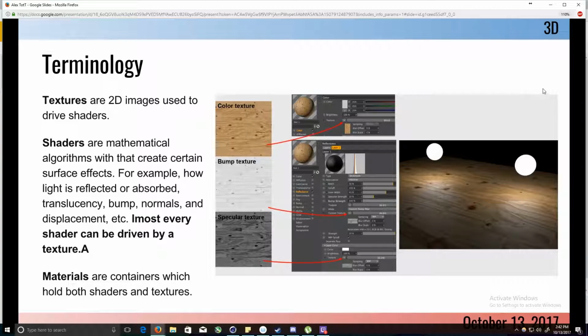So if you look at this little image, I have these 3 textures. One is a color, one is a bump, and one is my specular. And I'm loading these each into a different shader channel, such as reflectance or color or bump, and then they all are composed into this final image, which compared to using just a color texture, you wouldn't get any reflections on these little burn marks or on the cracks. It would just be a matte reflection. So it's important that you have these different textures working together, because just one isn't usually going to cut it if you're shooting for photorealism.